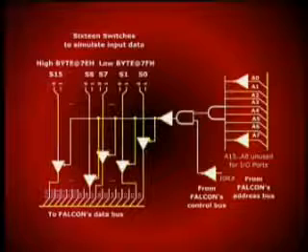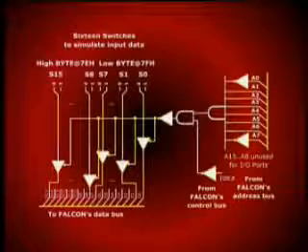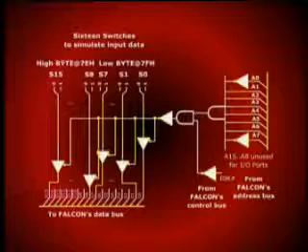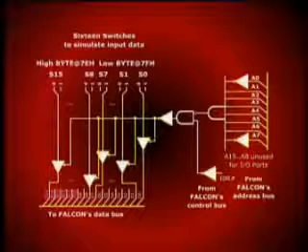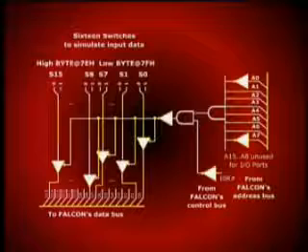The other AND gate takes the input from the previous 8 input AND gate along with A0 in non-inverted form, and therefore it corresponds to the address 7F.